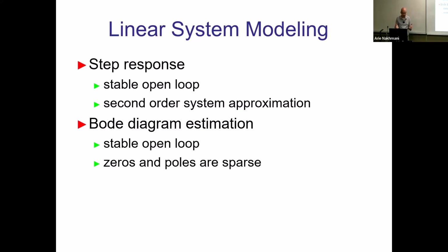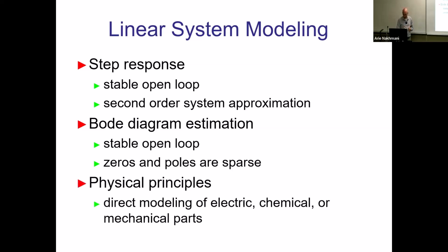Now, given Bode diagram, you can estimate back the transfer function. Because you know, like if it is going up, it's a zero, going down, it's a pole, things of that kind, okay? So you have all of these pairs of poles and zeros. So this is the second way to estimate it.